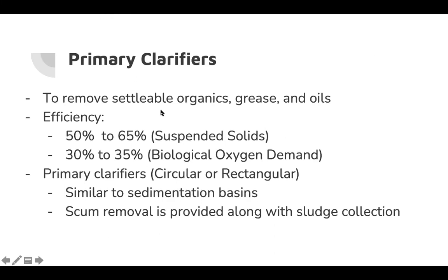For the primary clarifiers, it is to remove settleable organics, grease, and oils. As for its efficiency, it is 50% to 65% in suspended solids. Meanwhile, it is 30% to 35% for BOD or biochemical oxygen demand. Also, these clarifiers are shaped in circular or rectangular objects. And it is similar to a sedimentation basin, although the scum removal is provided along with the sludge collection.